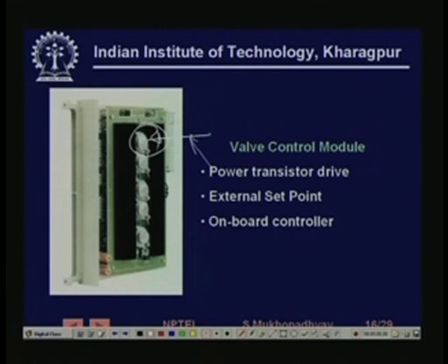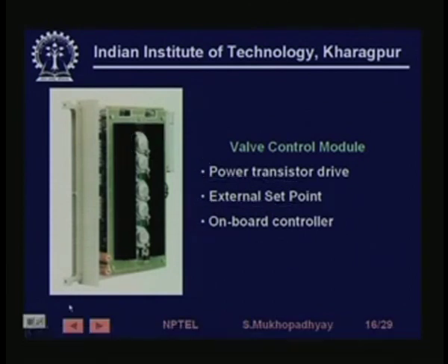For that it needs to provide a good amount of current, so you have these power transistor drives. It takes a set point from outside, so it interfaces to the bus, and the central processor gives it the set point, and it has its own onboard controller. So this is a typical valve module.